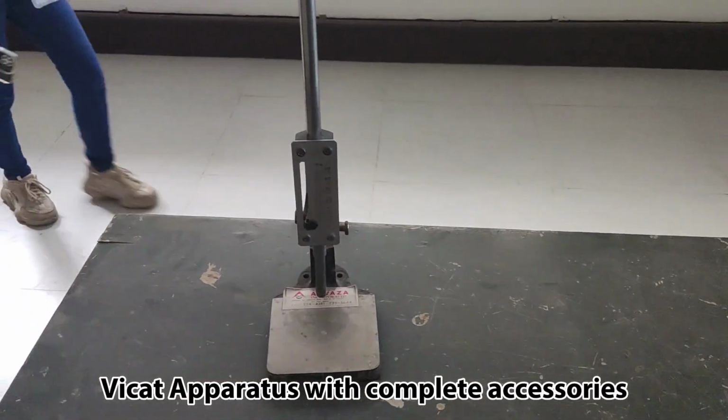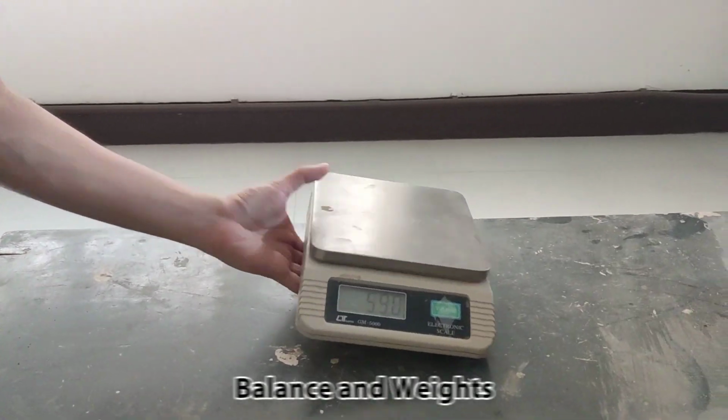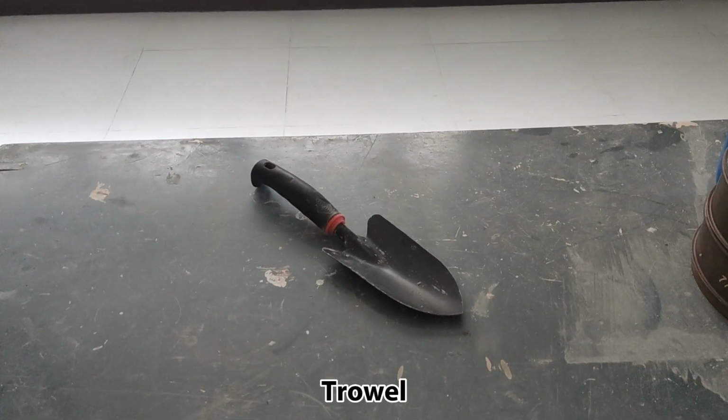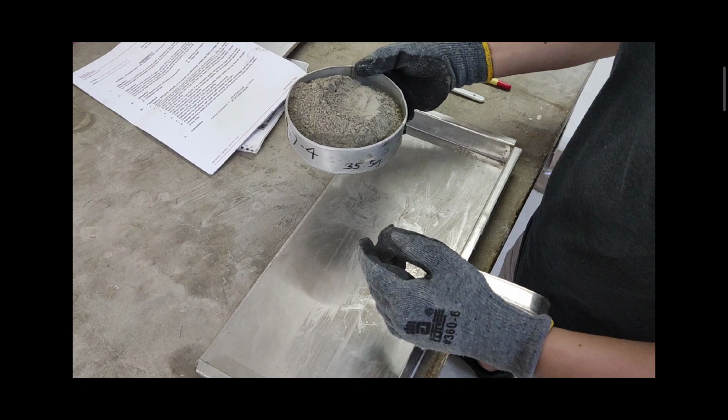So, what apparatuses will we be using in this test? We would be needing the following for the conduct of the test: Vicat apparatus with complete accessories, graduated cylinder or beaker, balancing weights, glass plate, gloves, trowel, and lastly, a non-absorbent mixing pan. Before we proceed, let me first give you a quick run-through of the procedure of this test.